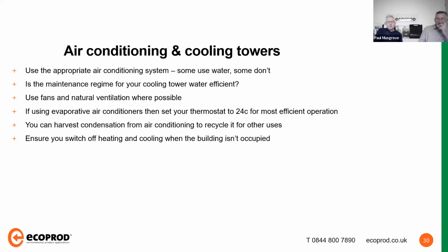Yeah, you need to consider what the quality of the water is you want to try and reuse here. Cooling towers and air conditioning, and we're even being asked about now the discharge from base exchange water softeners as well. Yes, all this water can be reused, but it needs carefully looking at. And you also need to ask yourself at the beginning, what's the driver for this? What's the water going to be used for? And that will dictate what you'll need to do to that water in terms of its filtration. Do you want to add to that, Jacob? Because it's quite a big subject, but it's very site specific, isn't it?